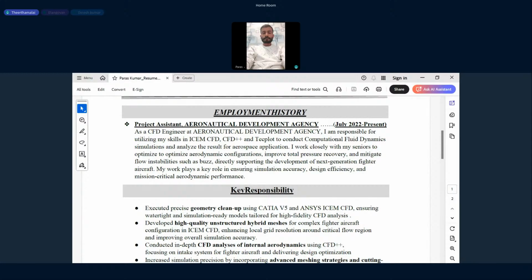But what is the disadvantage? The disadvantage is that we have to make the wing stronger to hold the intake. What is it structurally, aerodynamically? The boundary layer of the wing, where will it go? The wing boundary layer will enter into the intake. To avoid that, they have to put a diverter plate. So there are many other things we have to do.